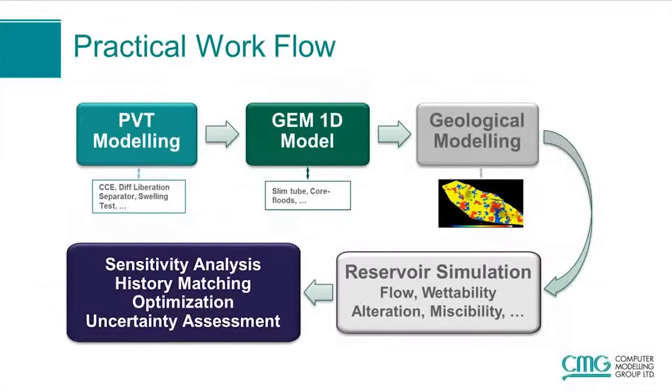The third step is geological modeling. In this step, you will distribute properties such as porosity, permeability, and clays in the reservoir. Then you take the PVT models and the geological model into GEM to make the base case reservoir simulation model.